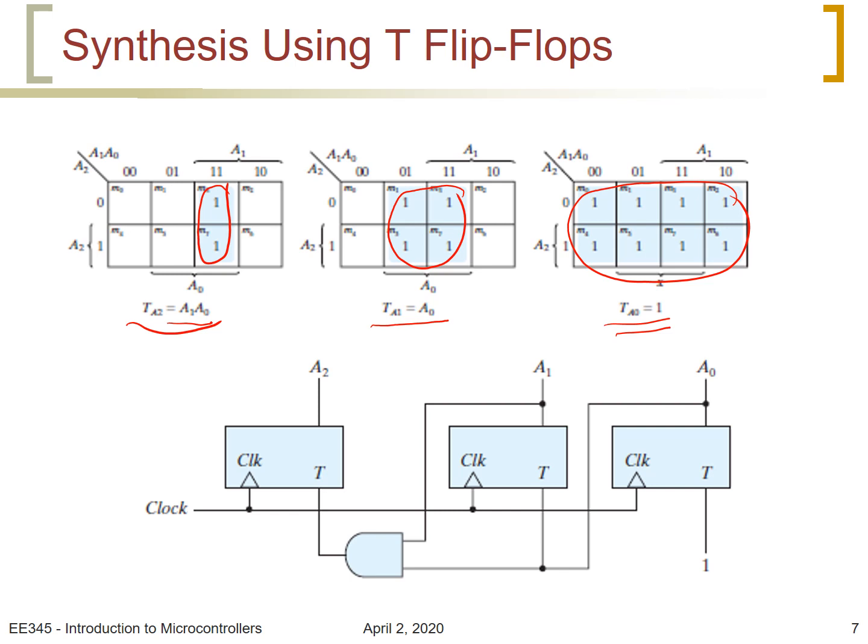With this, now the design is straightforward, because all we have to do is to draw 3 flip-flops. This is the first one with input T, and the second one with input T, and that's the third one with input T. And there is one common clock that's connected to all the flip-flops, as we can see here.